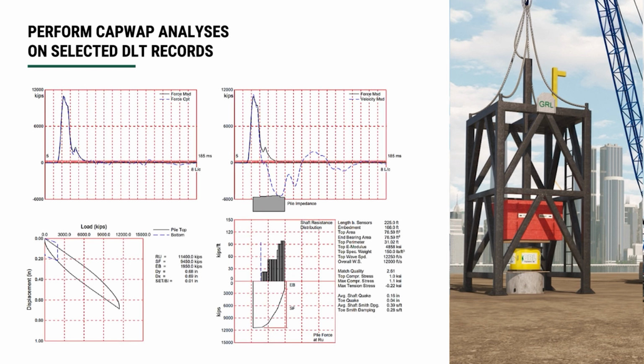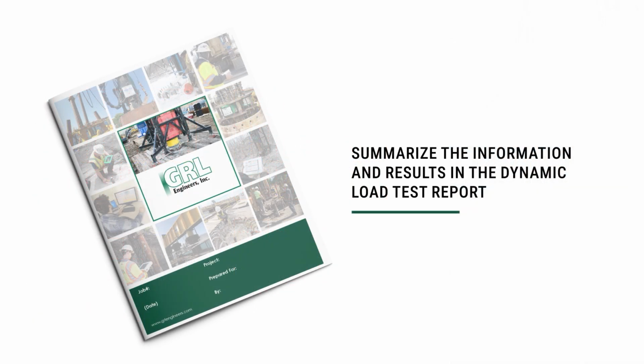With the background knowledge provided by the assembled project and test data, a CapWAP analysis is performed on select dynamic load test records to assess load capacity. Dynamic load test details and CapWAP analysis results are summarized in the dynamic load test report.